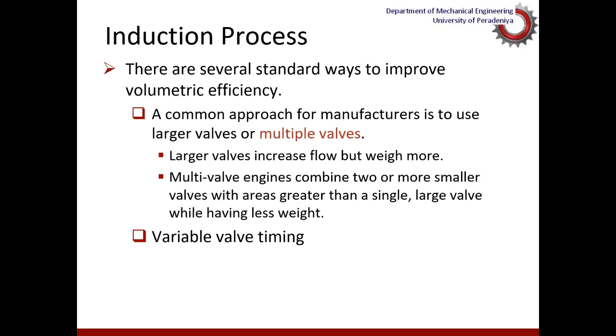Accordingly, there's another approach of strategically controlling valves instead of having static valve open-close timing, which we call variable valve timing, which enables us to ensure the highest possible volumetric efficiency under different engine operating conditions, speeds as well as loads.